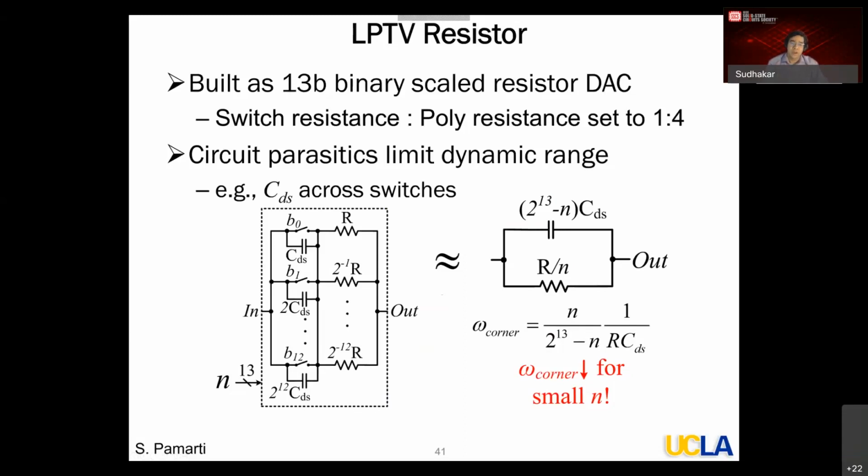That's good, but the switch is a transistor, so it can have some nonlinearity, so linearity may not be as good. If you make the switch larger, its resistance contribution will be smaller. That means the linearity will be much better, but you'd spend a little more power. We also played some circuit tricks here to take care of the effect of the capacitances.